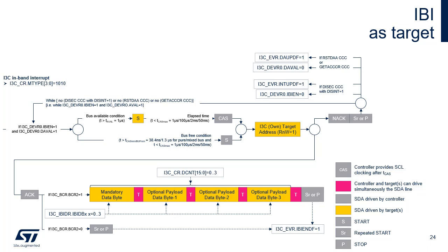or dynamic address resetting. In order to request an interrupt, an I3C slave shall emit its address into the arbitrated address header following a start but not following a repeated start. If no start is forthcoming within the bus available condition, then the I3C slave may issue a start by pulling the SDA line low and then wait for the current master to pull the SCL low.